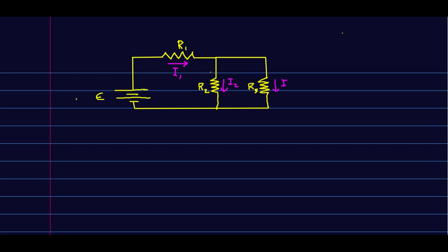One really important thing to realize about circuits is that changing any circuit element tends to change what's going on everywhere else in the circuit. So for example, here's a simple circuit with 3 resistors that I've called R1, R2, R3. And so they have currents through them that we might as well call I1, I2, I3. Let's think about what happens if we increase the resistance R3. Well, we'd expect that increasing that resistance is going to decrease this current.